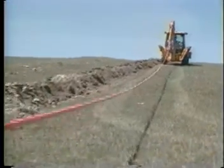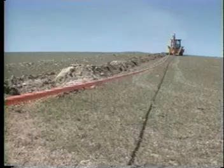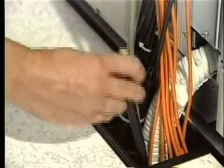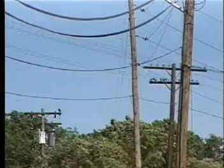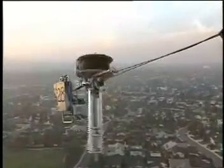From building entrance facilities, interbuilding cable can be directly buried, placed in underground ducts, or may travel in raceways placed in corridors or steam tunnels between buildings. Depending on the design of your fiber transmission system, your cable installation requirements may include indoor, outdoor aerial, directly buried, specialty cable, or a combination of these.